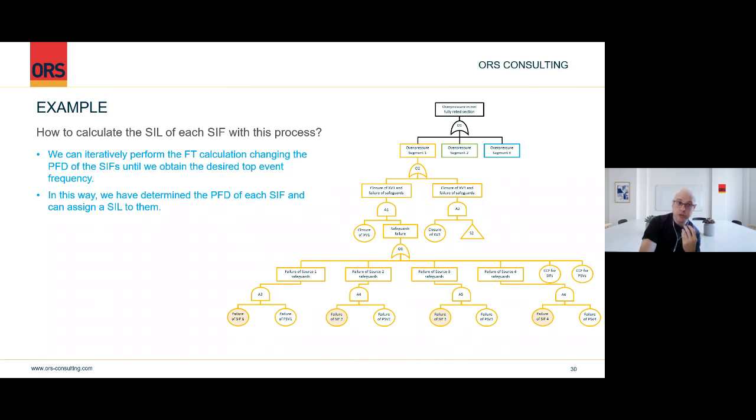And what normally most of these organizations do is you create sort of a risk matrix, and you calibrate, or you do a graph, and you calibrate it from, we say one fatality, for example, is 10 to the minus 5, which is more or less what the HSE says, right? So nowadays it's mostly considered 1 in 100,000 to 1 in 10,000 years is acceptable for a single fatality across different geographies. So you take that as a calibration point, and then you say, well, if I have 2 fatalities